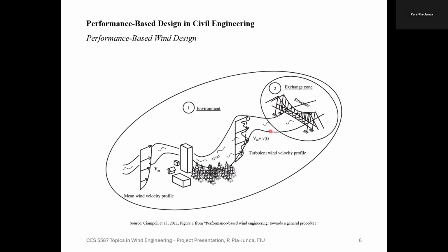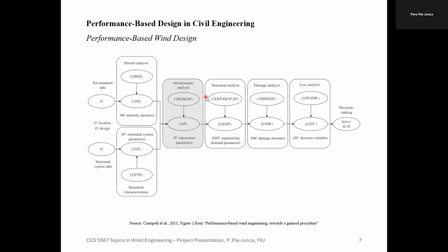Also, in wind engineering, there's the presence of the exchange zone, which is a region where the wind field and the structural response are strongly correlated. The presence of this exchange zone requires the addition of an additional module on the chain previously described for performance-based seismic design that captures this interaction between the wind field and the structure.